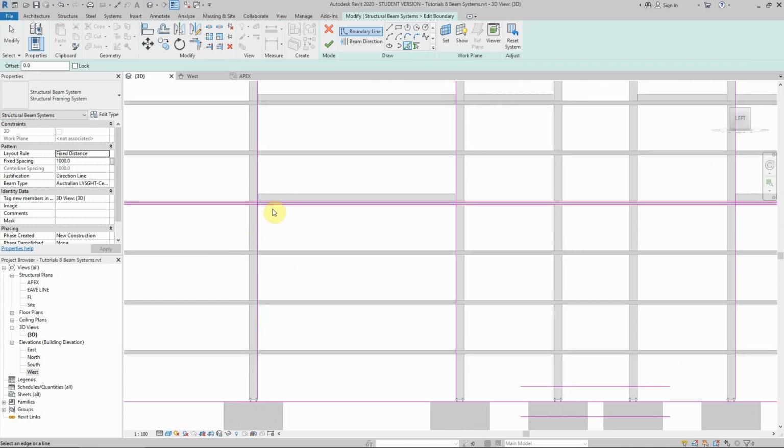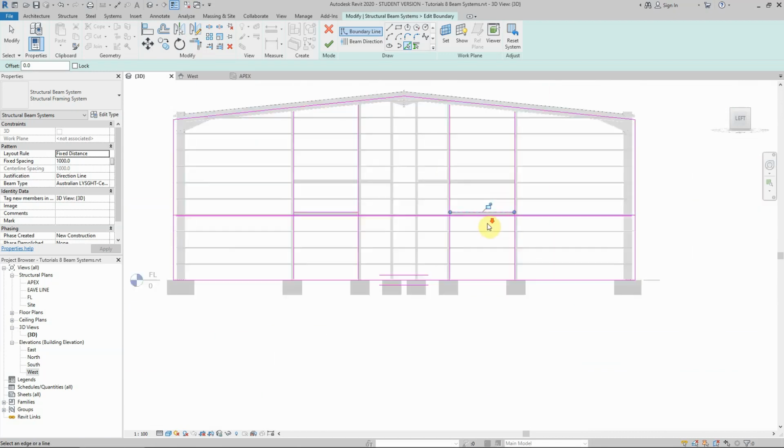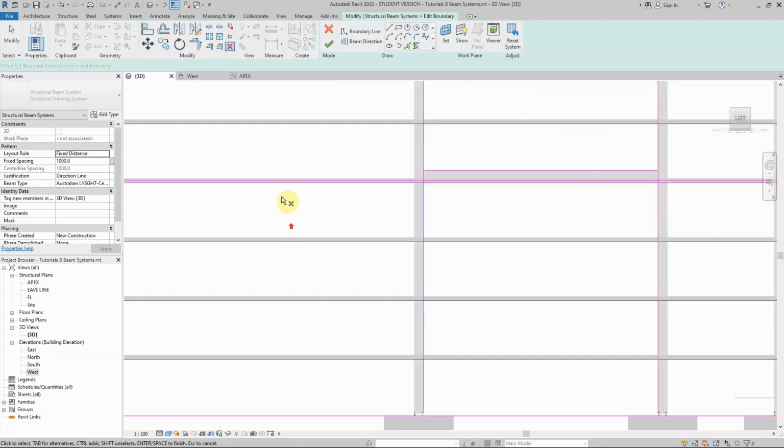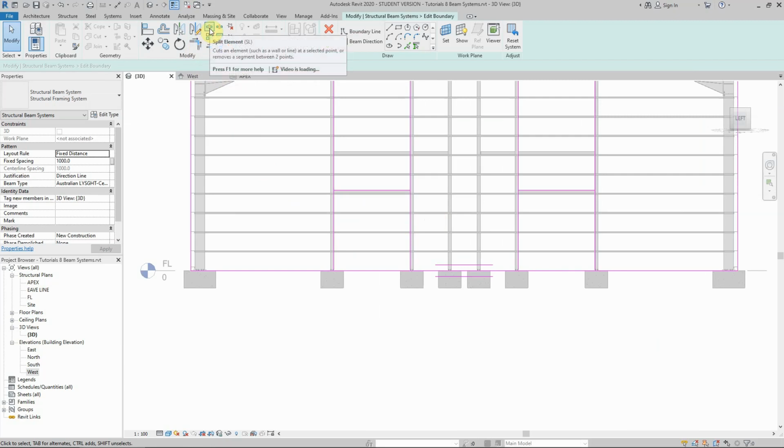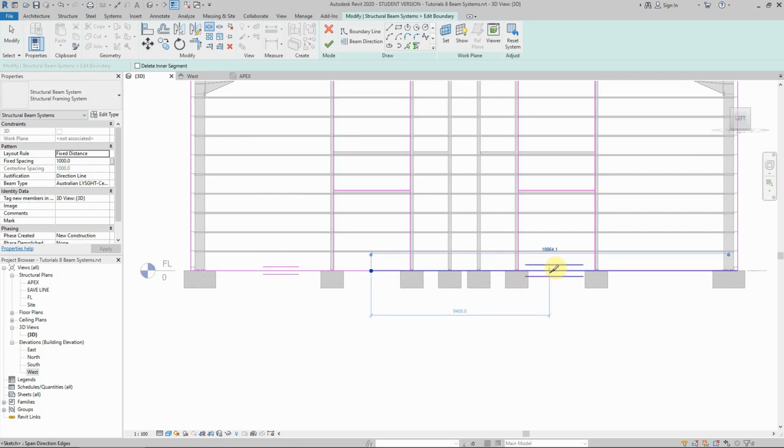What I'll do is choose that instead and delete the excess lines that we selected here. And using this split tool, I'll split this line here, you'll see why in a second, and this line here. Simply what I did, this line, instead of being a continuous line, I made into 3 different lines. The reason is so I can quickly use the trim and extend tool.